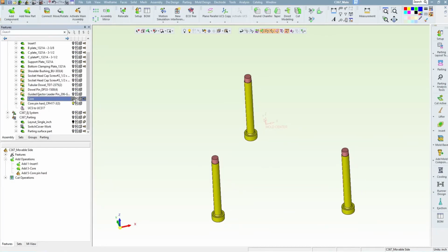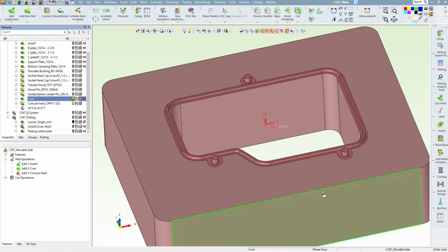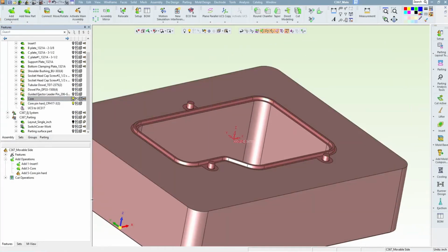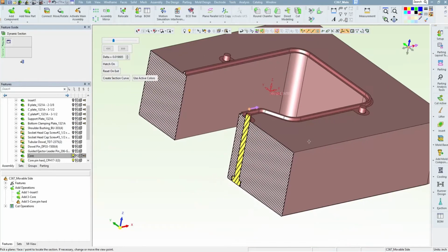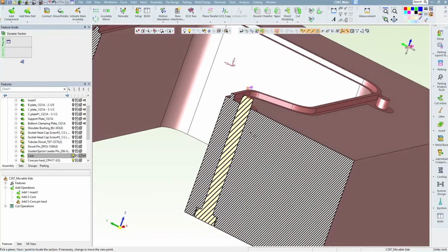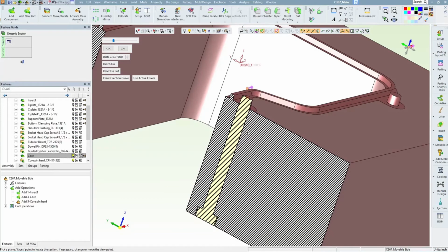Getting the shape on the insert directly from the work part, as opposed to taking it from the core block, is really ideal because it's a direct connection to the actual part. This is the best situation to have when the molded part gets changed and the insert has to be updated.